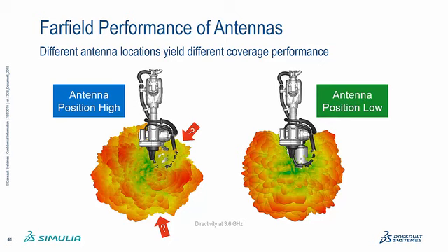And so this sort of information allows you to determine how many antennas you need on your robot, or for a particular operating behavior, how many different access points you need to place to ensure a continuous, reliable link to the industrial equipment, to the robots operating in our environment. So with that, it might have taken a bit longer than I was supposed to,